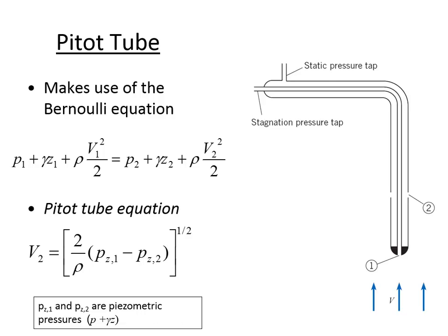And if you follow the tube, if you follow the center of it, then you'll notice that here is a stagnation pressure tap. So we could take some sort of a pressure measuring device and find out what's the pressure of air inside of the Pitot tube from that opening. And we assume that the pressure is the same everywhere inside of the Pitot tube.